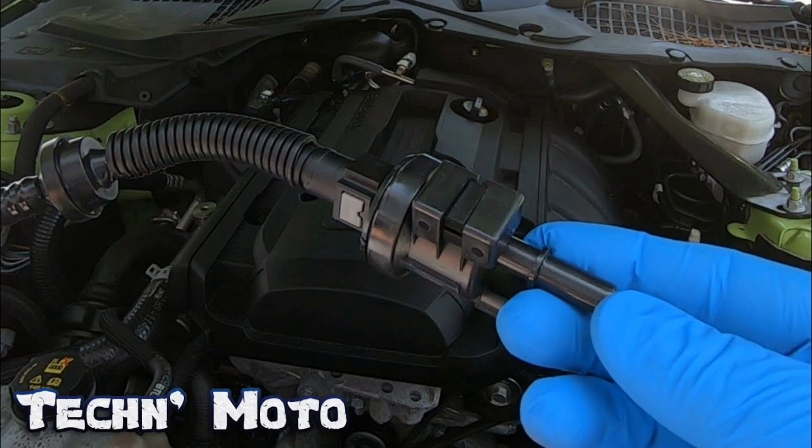What are the possible causes of code P0496? Code P0496 is often triggered by a faulty purge valve solenoid that remains open. Unfortunately, there are many other reasons why the code can be triggered. That's why it's a good idea to carry out a thorough diagnosis before replacing any parts. For a proper diagnosis, you can consult a certified mechanic.